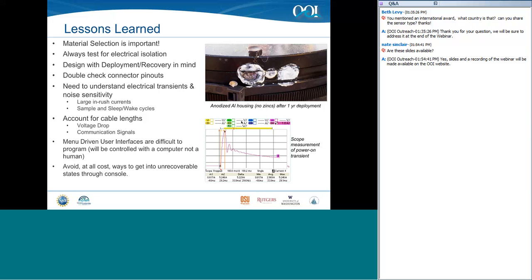We can also run into problems where, again, it's a low power instrument, but there's some mode that it can get into. Either it's self-calibrating or something else, and all of a sudden it'll use a whole bunch of power and cause an overcurrent condition. And so trying to make sure we exercise the instrument through all of its different modes as close to the installed environment as possible is really important, because we don't want to have to figure that out later after it's been installed.